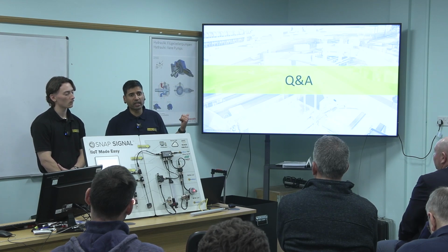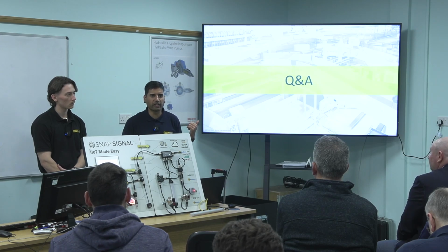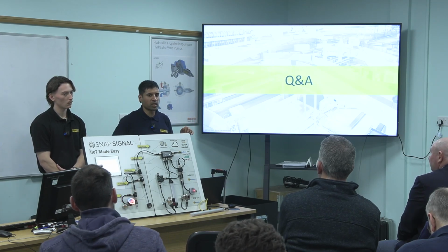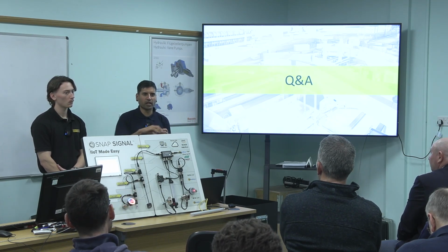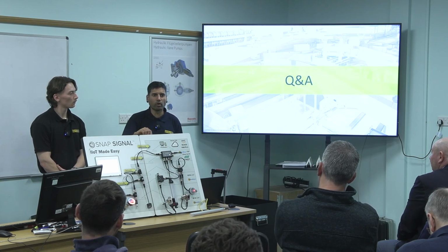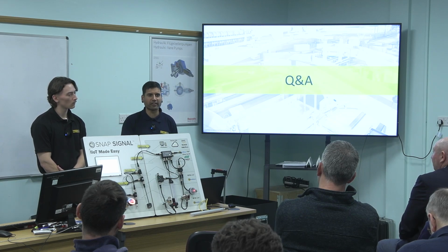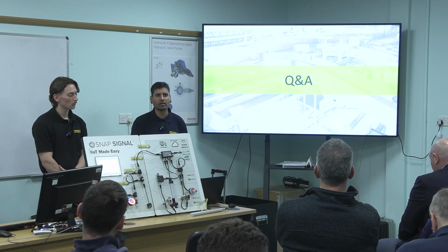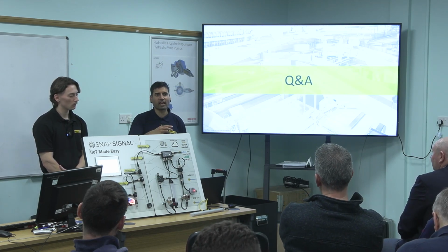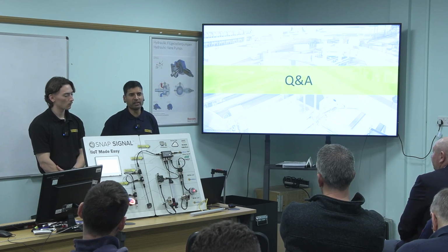Even with IO-Link, I think it's 32 bytes on IO-Link. Sometimes we use our IO-Link master to convert to Modbus, but we take out the signals we want, because we don't want to take everything out of IO-Link, as there's a lot of parameter data, diagnostic data and process data. We just want to take out of the IO-Link device the data we need.